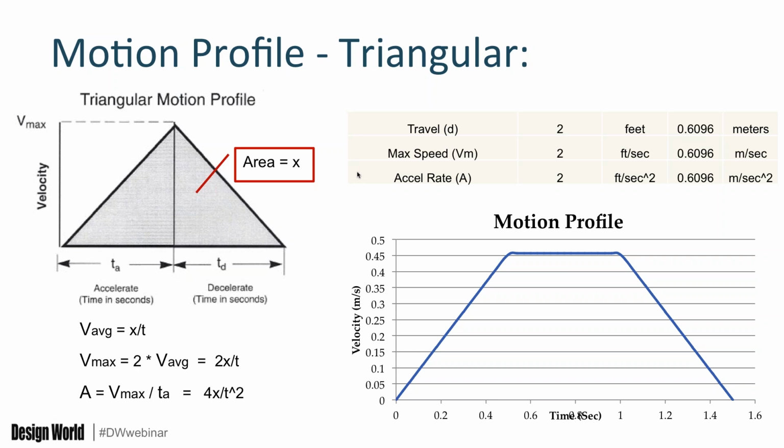In the case of a mechanical programmable indexer, you can use one part number and you can program the displacement depending on what the application needs. So the flexibility of the programmable index displacement is a luxury for designers who require the changeover at any given time.